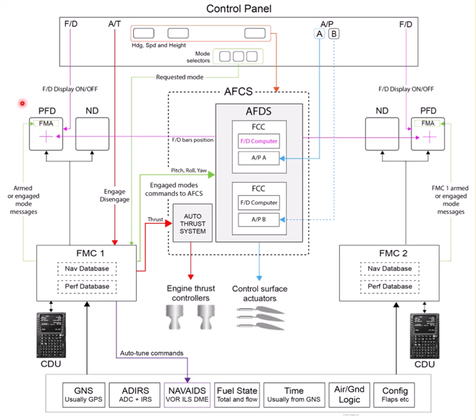So we'll possibly select a heading, just fly towards the localizer and intercept the localizer. So that's the runway centerline dealt with. And then at the right height, we'll approach the airport, we will intercept the glide slope from below, and then we'll fly down the glide slope. Now the flight director can get us to do that. The flight director can guide us to find and fly down the correct approach path to the runway. We're still going to have to manually land, we're still doing the throttles, we're still doing the gear and flaps.